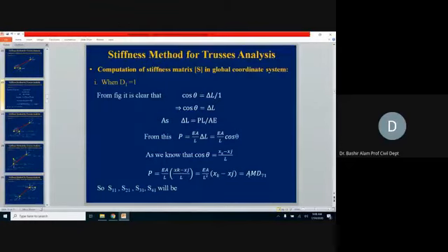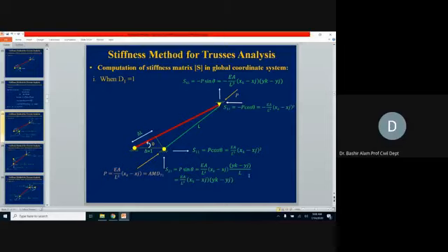So when we give a horizontal displacement at joint 1, we produce S11, S21, S31, and S41, and similarly the AMD of the member by this one displacement. We found this P, the member force, which is equal to EA over L square times XK minus XJ, which is also equal to AMD 71 here.